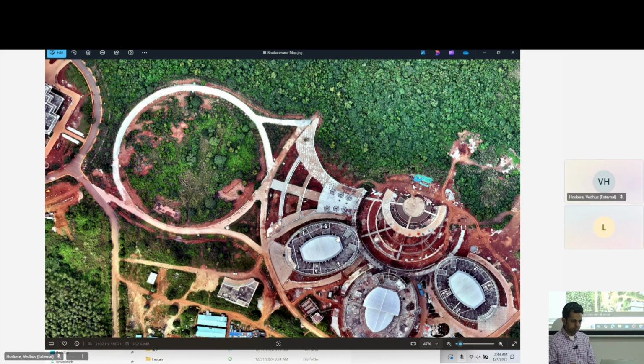So with the drone, what are the angles that are possible? You can go... yeah, because we're looking down, so it's fine. So maybe we can do 60 degrees, and then we need to set the speed, and we need to set the overlap.